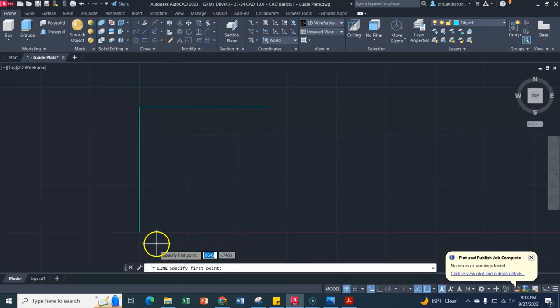So I'm going to grab my line tool again. You notice there's a little square that pops up that will lock it right onto that initial part of our line. Oh boy, what is this? I'm going to have to do some math. 8.0 minus 2.5 is 5.5 inches, and I want that to be at 0 degrees, so I'll do 5.5 Tab 0, Enter. I'm going to go up 2.5 Tab 90.